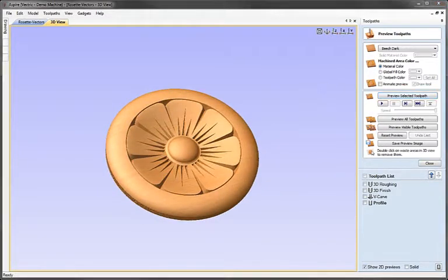Project toolpath onto 3D model is available for most of the 2D and 2.5D toolpath functions within Aspire. There is one thing to note when using this option though, and that's that the software is projecting the center of the tool onto the 3D part and not gouge checking the complete shape of the tool. As such, you are limited to projecting onto shapes that don't have sudden transitions of depth or have very high angles on them. The result of this toolpath will be accurately shown in the 3D preview though, so just make sure to use that in order to check what the result of this is going to look like before you machine it.